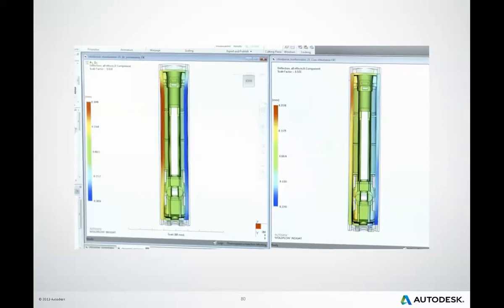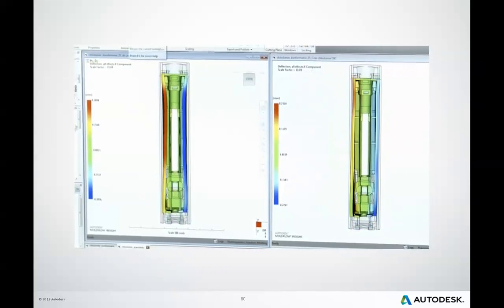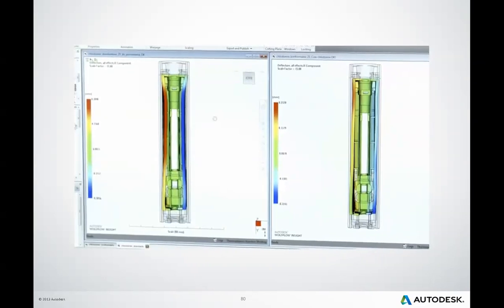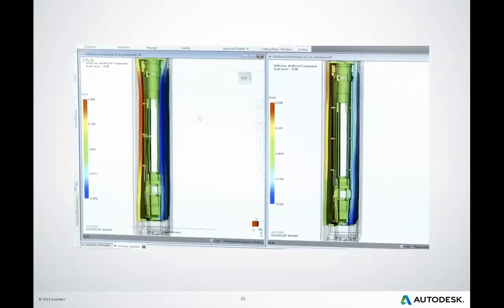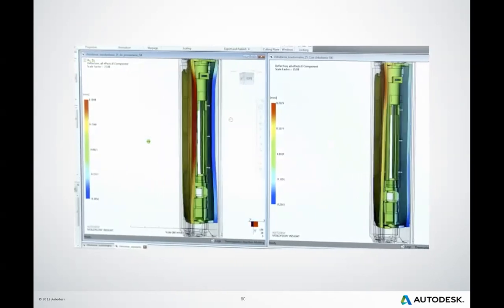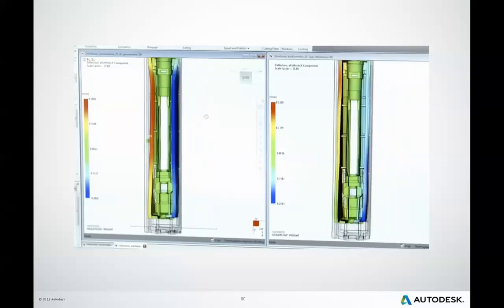Providing uniform heat transfer from injected parts not only reduces the cycle time, but also minimizes warpages and part deformations that might appear due to uneven temperature distribution. On the other hand, implementing conformal cooling is financially justified mainly in the areas that are beyond reach for conventional methods of production, or in the case of high volume production.